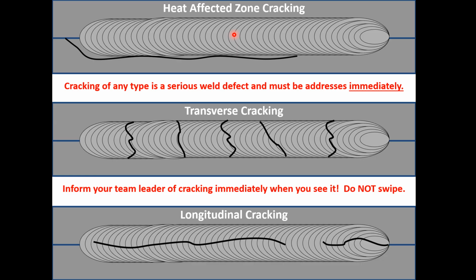Now, the first thing I want you to know about this is, remember one of the rules I said before, you can't put weld metal where weld metal is not supposed to be. If they've told you that that's a 3 millimeter fillet or a 4 millimeter fillet, and you've got to start coming out here, way out here, right? That's a stop. You're putting weld metal where weld metal was not supposed to be at this point. The base metal has been compromised outside of where the weld's supposed to be. That's junk, right? Don't even give that one a second thought.